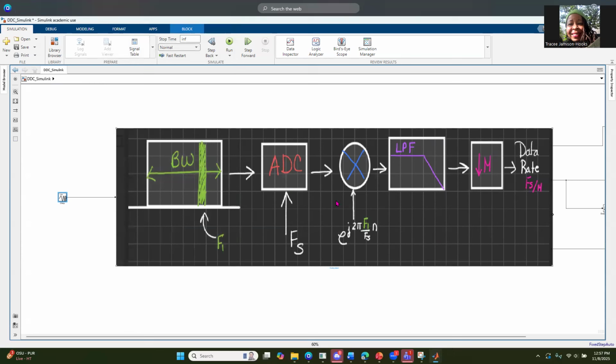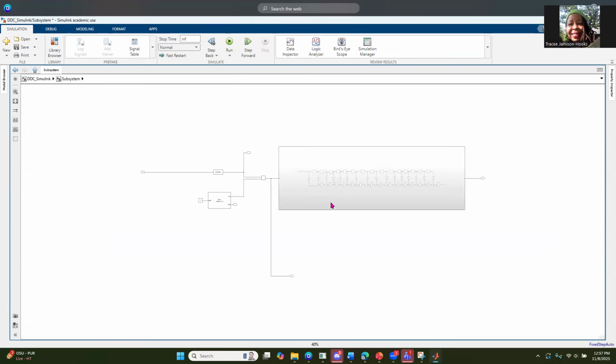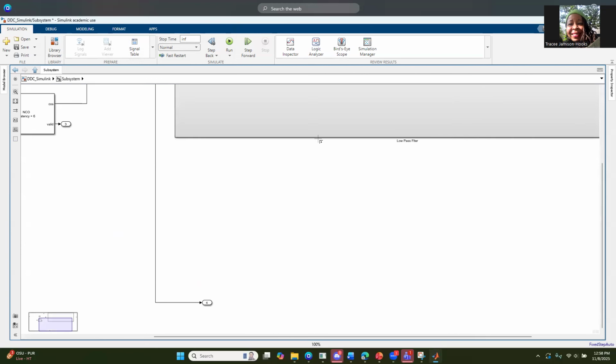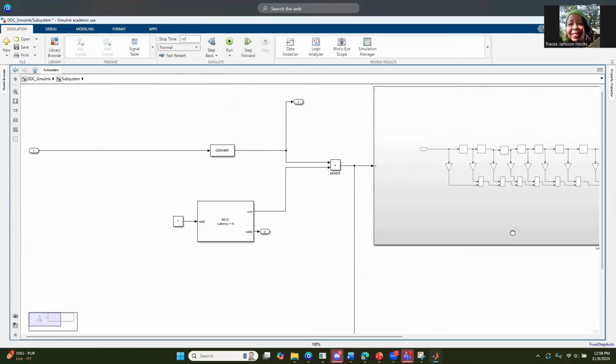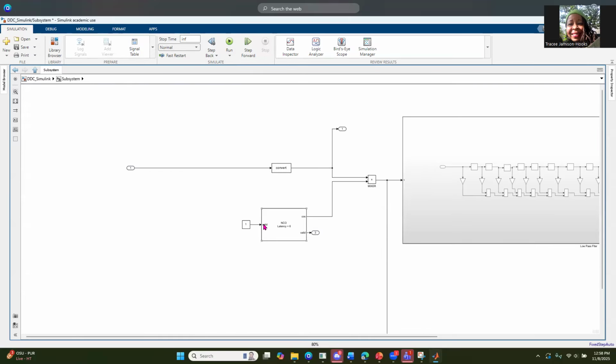And now we go inside, under the hood of our design. And again, Simulink models are really good to create when you're trying to put together a fixed point model of an implementation you want to deploy on an FPGA, and you want to just check to see if your timing parameters would work, or you have enough resources.